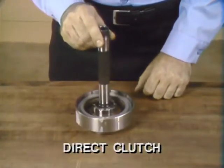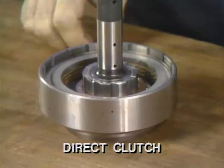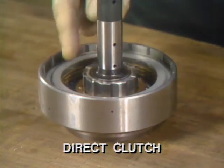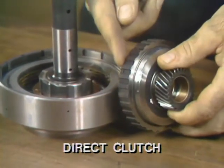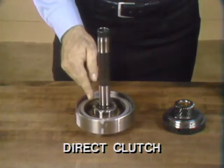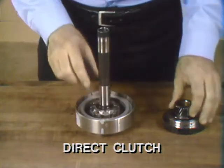The direct clutch is used to bypass the freewheeling feature of the one-way clutch. The plates are installed in a rotating cylinder which is integral with the turbine shaft and the one-way clutch inner race. And the sun gear outer race assembly has external splines that mate with the internally splined friction clutch plates. You can see that the direct clutch completely surrounds the one-way clutch.